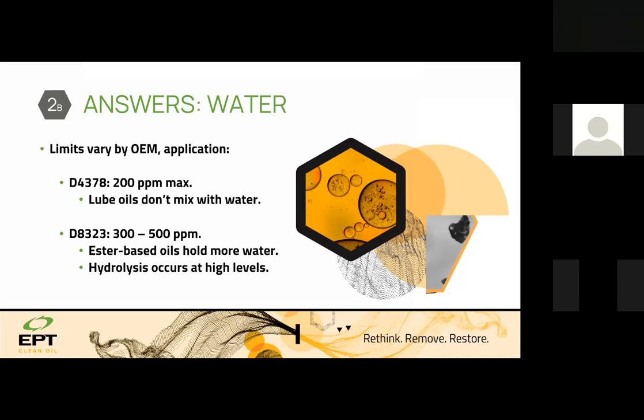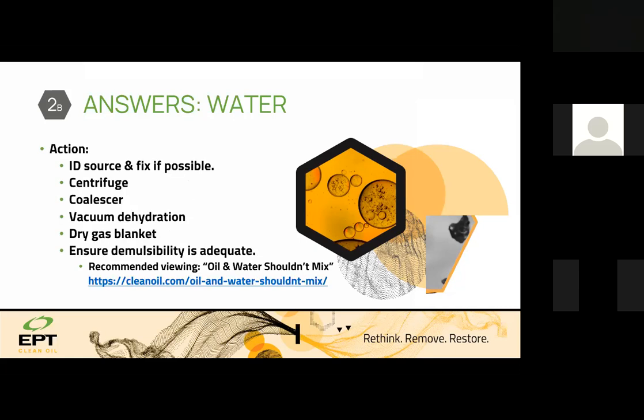So we are worried, for example, when it is near the seaside, that the air around the machine has moisture inside. These oils can absorb the moisture in the air on top of the tank into the oil itself. So we need to be careful about ester application. And then for water, once we identify it in the machine, we need to carefully find the source. Identifying the source is the next step. If it's coming inside, we need to rectify that and then fix it.